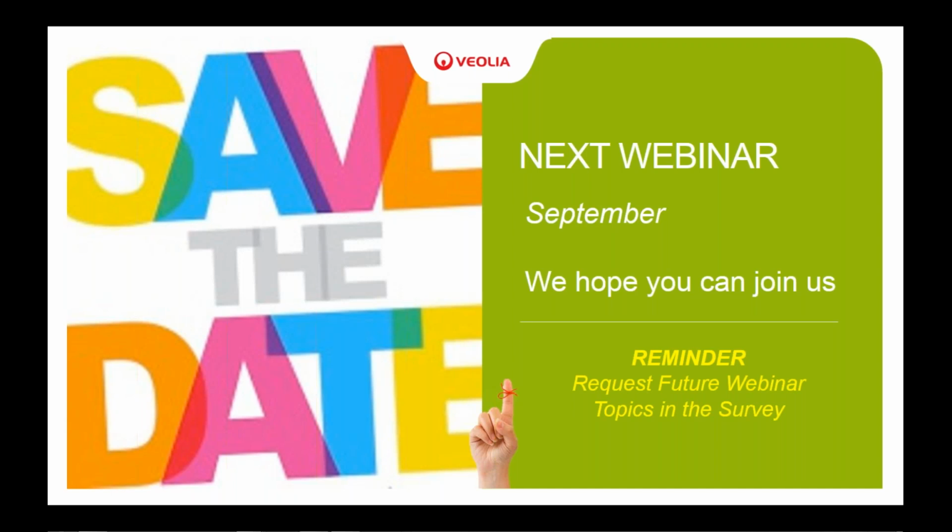We do that in our lab. There's some other people out there that do it, where you can send a sample of sludge in, we can run an activity test on it, we can tell you what the maximum activity level is, and if you have one of those done every 6 months, then you will have a back case history. That way, if one day your system isn't working well, you have something to look at for what it should be operating at.